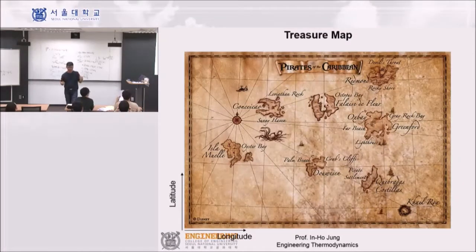So in the phase diagram, you can assume that this is the phase. Which phase do I want to have? I don't want to have this phase; I want to have the other phase. And in the phase diagram, for the x-axis, instead of longitude, typically we are using composition, and for the y-axis, instead of latitude, we are using temperature.